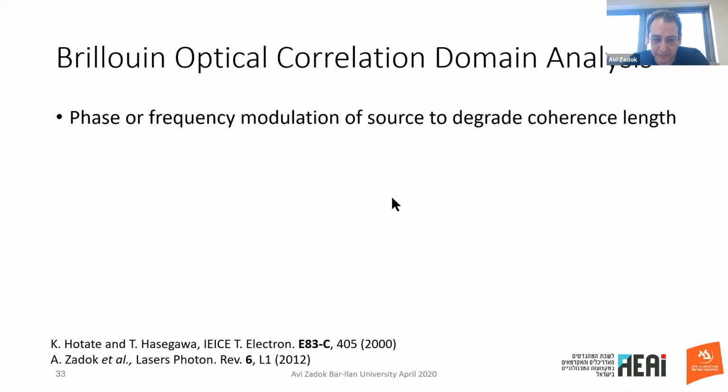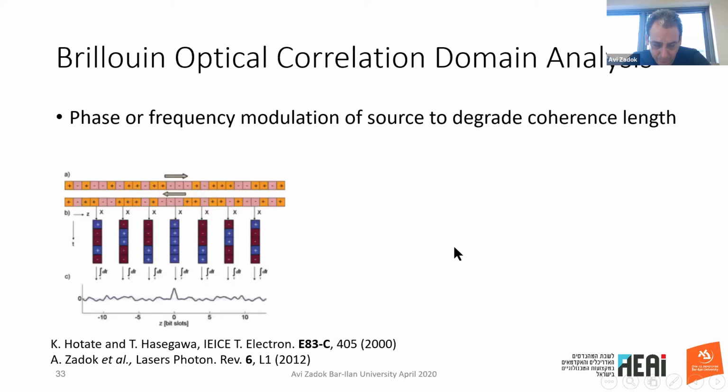This principle was proposed first by Professor Hotate from University of Tokyo in year 2000. What I show you here is a variant that we extended in 2012 in my group with collaboration with EPFL. So we're modulating the pump and signal with a phase code. The pump that goes in one direction is a series of plus and minuses alternatingly. And we're launching the signal wave from the opposite end with the same sequence in reverse.